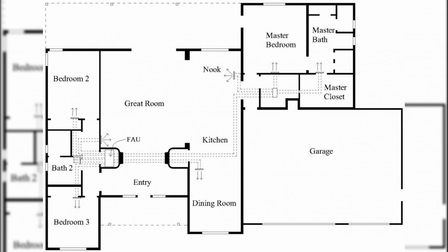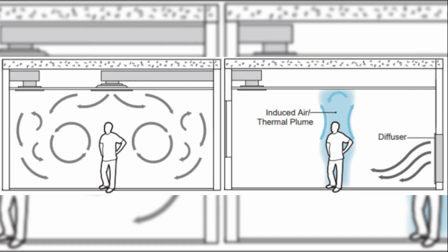At low airflows, 30 to 50 CFM, most residential registers are oversized, leading to poor performance. Register selection must be matched to the specific airflow and throw requirements of each room. The DOE CFD simulations confirm that higher velocity air delivery creates better room mixing in both heating and cooling modes.